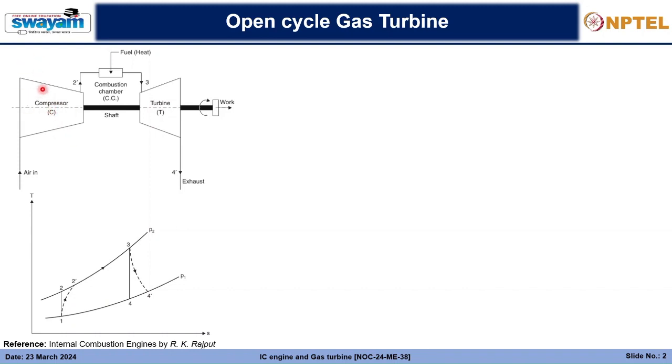Just imagine that while compressing a gas, heat is produced, and if we could contain it perfectly inside the compressor, then exactly that heat would be utilized in increasing the enthalpy of the gas. But the heat is not perfectly contained in the compressor, and in the turbine also, and therefore there is a heat loss.